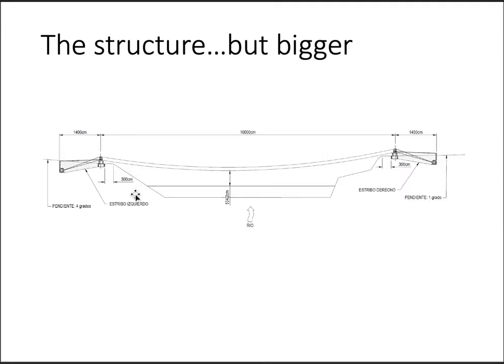But let's take a look here at another example. So you can see this is essentially the same thing, but here we have a 100-meter span. But again, you have one bank here, edge of bank, slopes down. You have the gorge here, your high water level here, and the same thing on this side. And so do note here, instead of the abutments being, I believe, 9 meters back from the tower on the 25-meter span bridge, here we have 14, right?